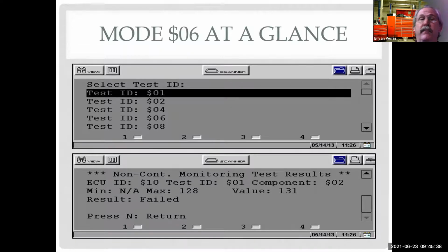So certainly, our driving can definitely affect whether it runs or not, but also affect the results based on what we're doing. My converter is going to look different if I have a truck that's full than if I have a truck that's empty. My calculated load's going to be different. So even though I have a range that I'm allowed to test, if I'm at 20% versus 60%, we're probably putting different emissions into the cat that could affect the result on the cat.